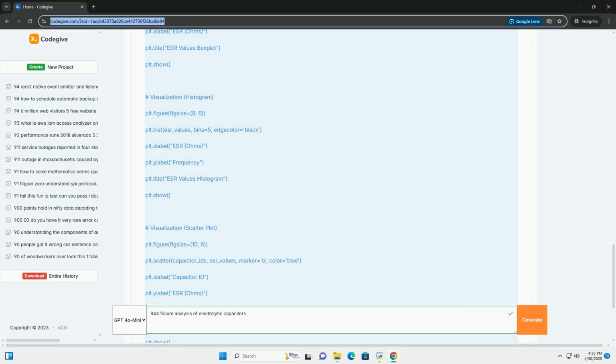The capacitor may become warm or hot, especially at higher voltages. Increased power consumption, and potential damage to other components due to the increased current flow. Can cause voltage regulation problems. Impact. Can overload power supplies and potentially damage sensitive components connected to the capacitor.